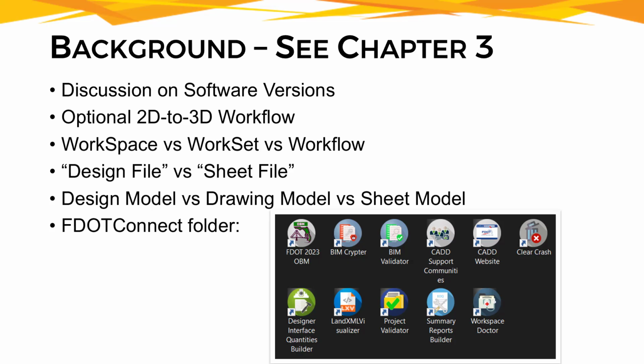I'd also like to mention that starting with OBM 2023, Bentley allowed the use of an alternative workflow where the 2D decorations can be placed in a separate model, closer to the ORD workflow. Although not included in the FDOT Bridge Design 3D Modeling and Plans course guide, we posted a standalone white paper and accompanying video explaining the alternative 2D to 3D workflow.